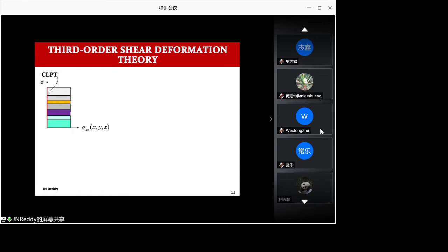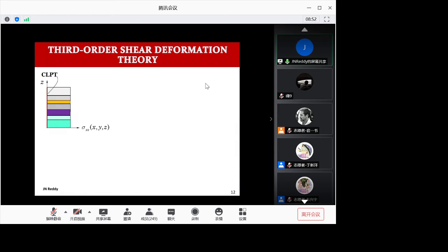As a result, we under predict displacements, over predict stresses, and especially buckling loads. So these are not very conservative because we know the structure will fail before your theory says it will fail, and that's not good. If anything, we want the theory to predict that the structure fails before it actually fails. So that gives a little bit of room for, what you call, safety.